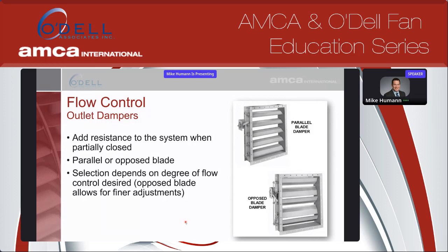The parallel blade damper will bend air to one side of the duct for a little while. And it's also not as precise as an opposed blade damper. Opposed blade damper is a little bit more expensive. Air comes out a lot more uniformly, and it also gives a much more linear curve of the change in airflow as you close the damper. A parallel blade, at first, when you start to close it, doesn't change much. And then it really drops off once you get to about halfway closed. So it's not a linear curve.